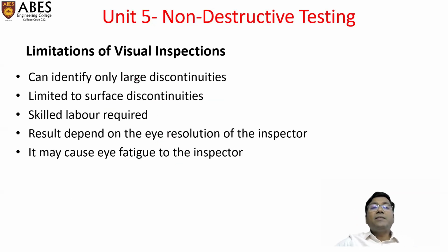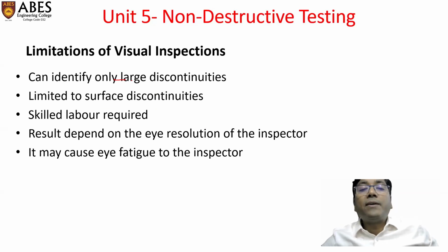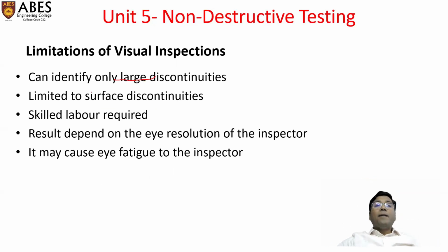But what are the limitations? We can readily say that it can identify only large discontinuities, and is limited to surface discontinuities. Skilled labor is required. Results depend on the eye resolution of the inspector, and it may cause eye fatigue to the inspector.